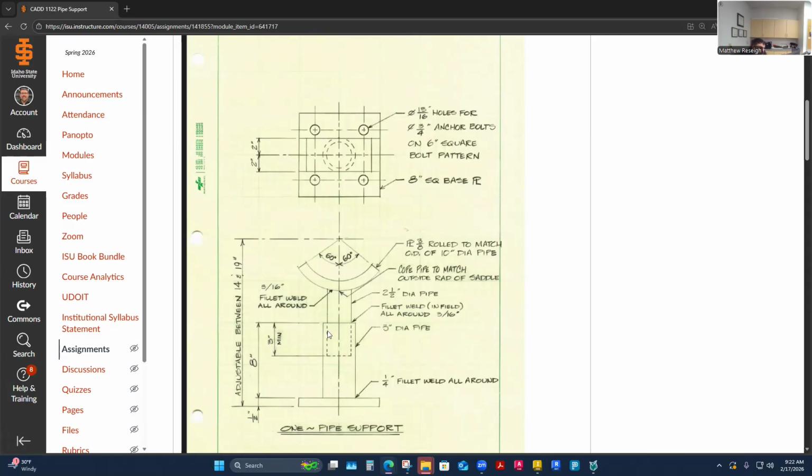There's maybe a minimum distance that this can be. I wouldn't want this to pull out any further than 3 inches and potentially become not structurally supported well enough. For whatever reason, we've determined that 3 inches of overlap is the minimum. I can have more than that, so this thing can drop in from there. But I don't want this thing to ever pull out to hit a height that decreases this minimum relationship here.